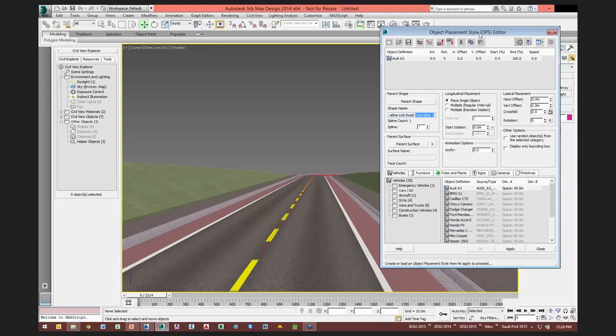Another question came in, how does the road marking style handle multiple regions where feature lines might be discontinuous? When I'm selecting the edge of travelway feature line, I'm not picking a single object, it's more like I'm referencing the point code of that feature line. That's why I put stripes on both of those feature lines. So I actually had 2 ETW feature lines in there, and it assigned it to both of them. So it's kind of like a Civil 3D corridor code set style in that you assign styles to certain codes, and it applies to all of those codes wherever they're found.